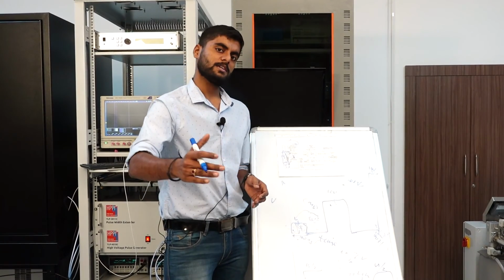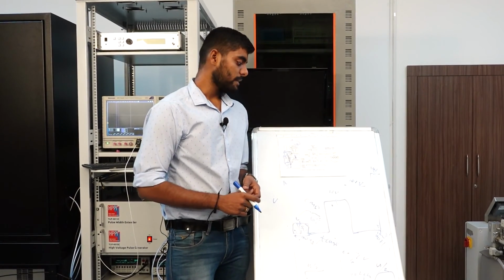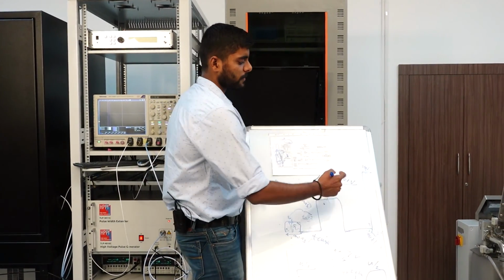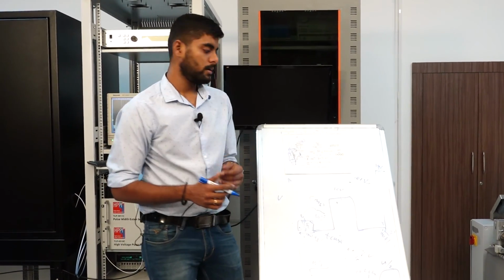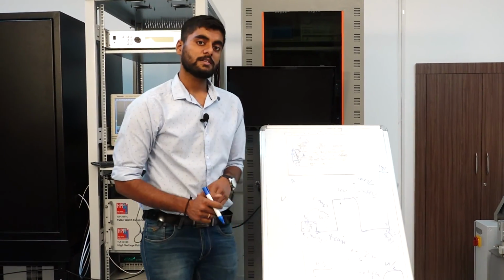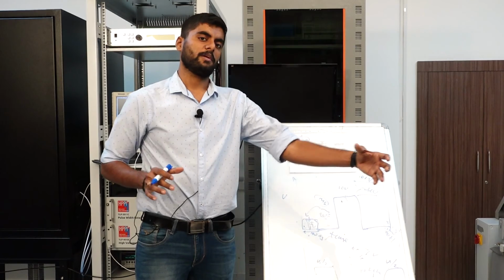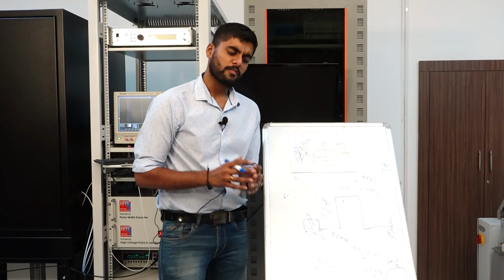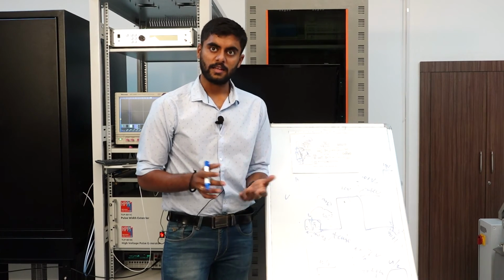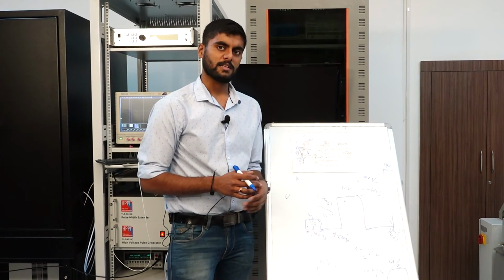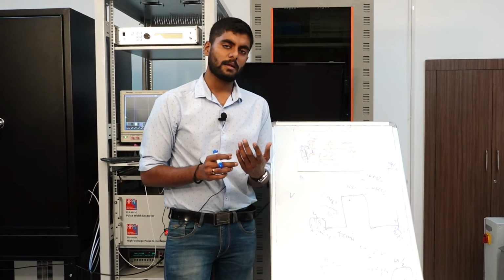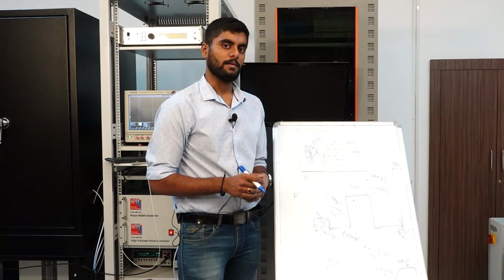It may be gradual in nature over different voltage pulses, and that's important to know, because then your device, when you're applying an instant pulse, might actually go beyond 2 kilovolt signals, because there's no soft damage taking place over a period of time. And you would see in a lot of reliability techniques that damage that looks instantaneous is not actually instantaneous, it's more gradual in nature, and that is very common in dielectric breakdown as well.